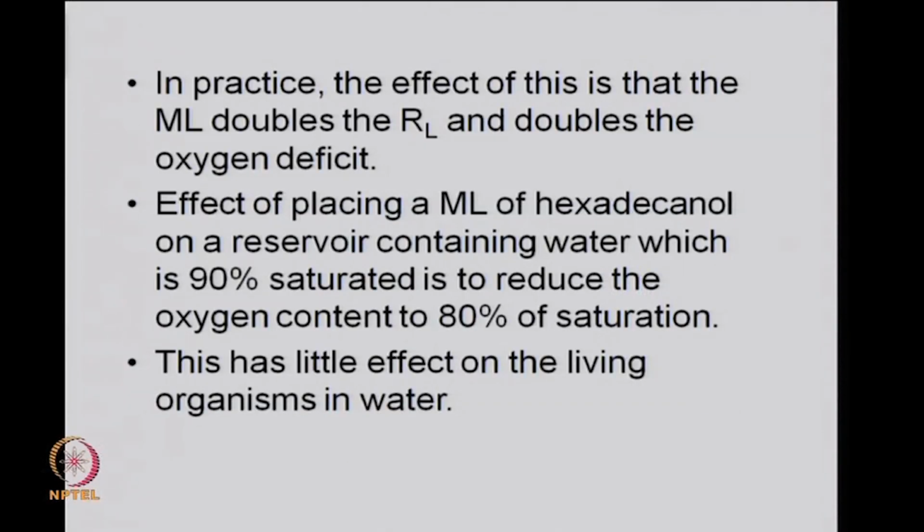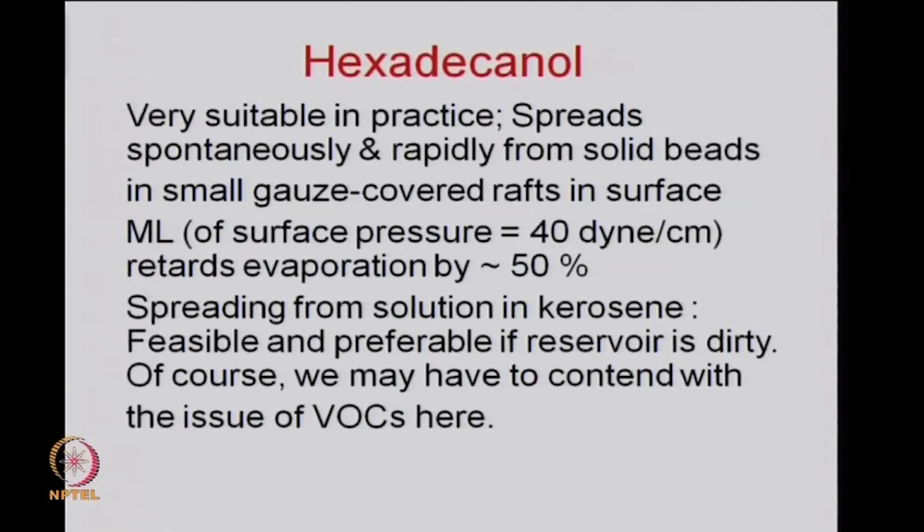We had seen that cetyl alcohol, or hexadecanol, is effective in containing the evaporation losses without sacrificing on the dissolved oxygen concentration level in large water bodies. So, we talk a little bit further on this particular compound, hexadecanol. We will quickly review in a couple of slides the performance of hexadecanol and some of the practical aspects which might appear surprising.